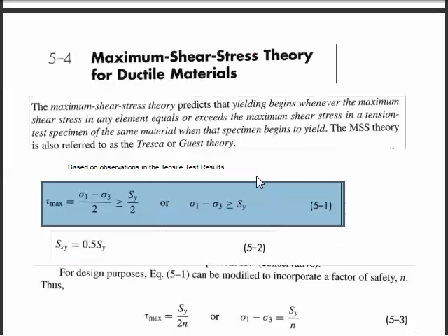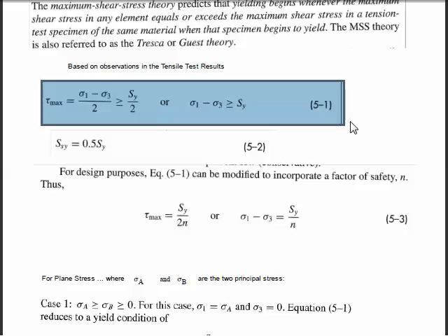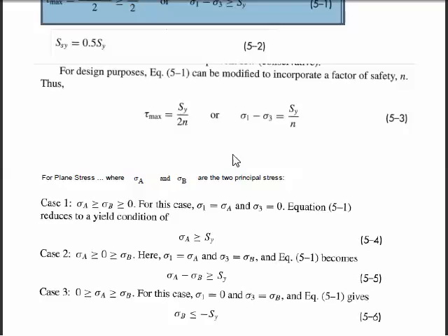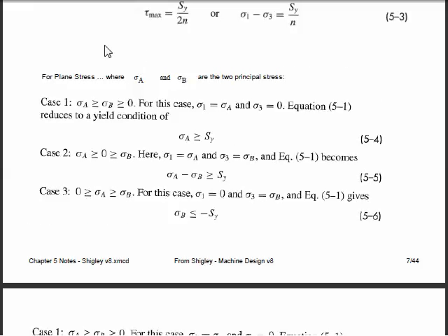So, the first one, maximum shear stress theory, we've been talking about all semester long, and of course it comes from the Mohr circle. I'm simply going to point out that we have a very simple set of equations to use to test the maximum shear stress theory, and it has to do with values of sigma A and sigma B. Let me remind you precisely what those are.